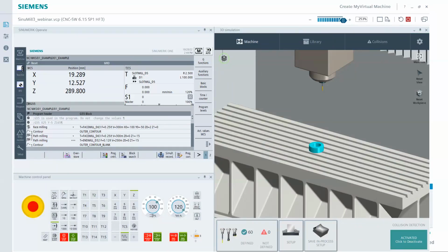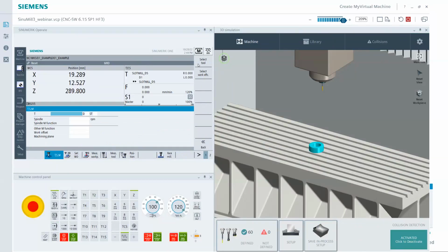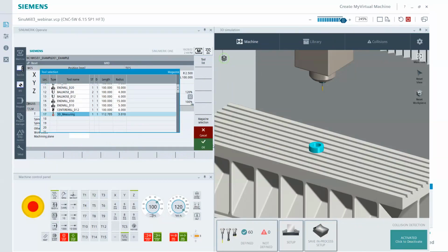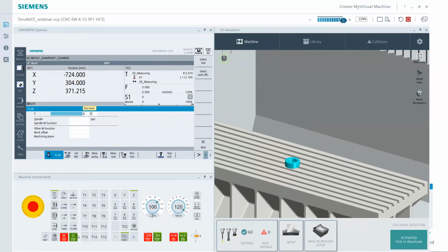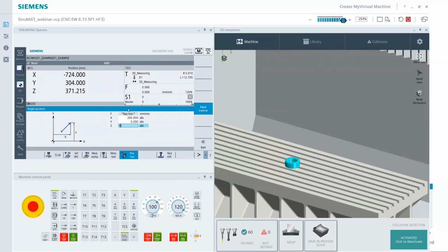and we can load up our probe. So I'm just going to run over to jog, do a quick tool change, just like I was on a real machine. Cycle start, and actually the calibration process is exactly the same as if it was a real machine. I'm going to position, and now I know that the middle of this happens to be sitting at, we'll do 100, maybe 200, 0, and we'll stay up from it a little bit, 10 mil.